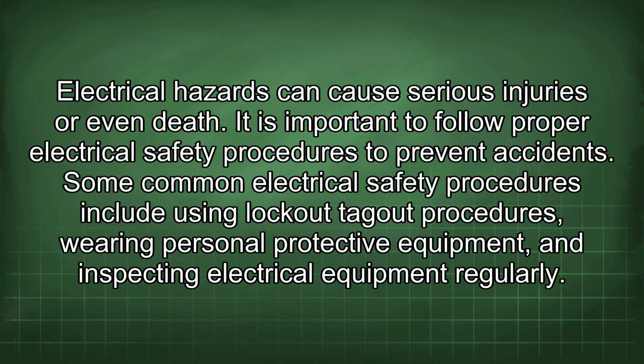Electrical safety is a critical concern in any workplace. Electrical hazards can cause serious injuries or even death. It is important to follow proper electrical safety procedures to prevent accidents. Some common electrical safety procedures include using lockout-tagout procedures, wearing personal protective equipment, and inspecting electrical equipment regularly.